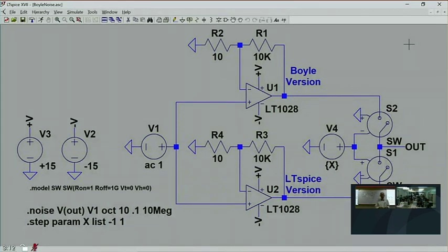My job was to make the preamplifier. By the way, when you measure the rock resistivity, you do it inductively, because around the borehole, you've invaded the borehole with conductive stuff because of the process of drilling, so you have to measure the rock through a few feet away from the borehole. That's done with antenna coils. You set up eddy currents and you measure that. And my job was making preamplifiers for these antenna. Okay.